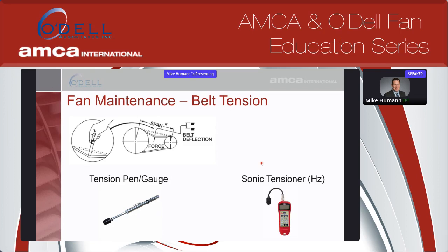Another way, a newer way that we've seen a little more frequently, is a sonic tensioner, and that's using frequency. Any belt has a natural frequency, and the frequency range for the proper tension is something you can get from the belt vendor and on belt selections. So a sonic tensioner is another way to measure belt tension.